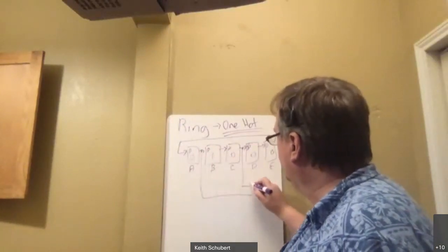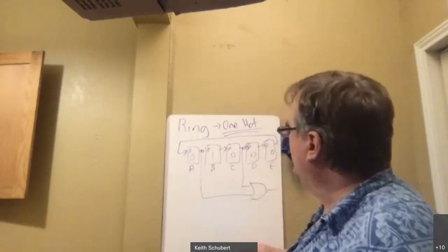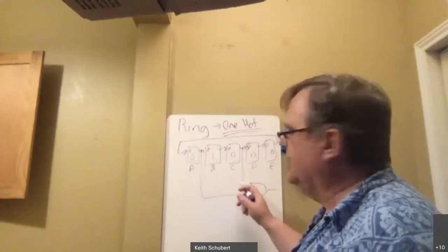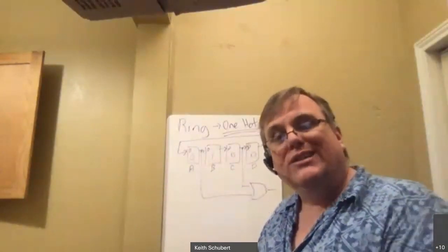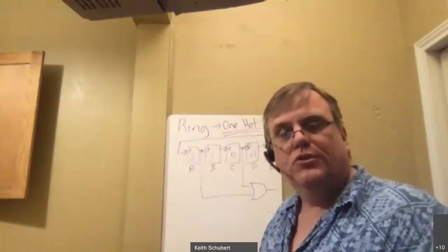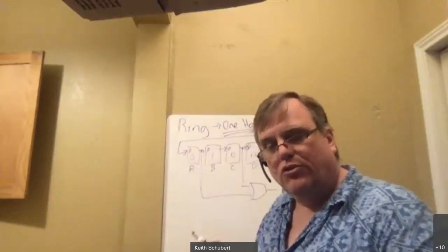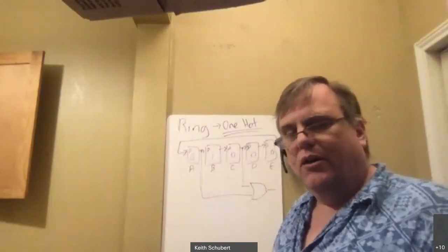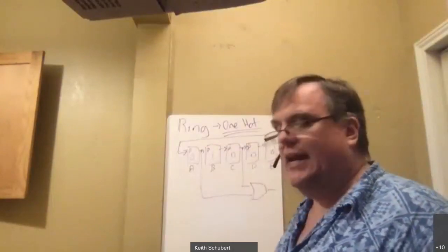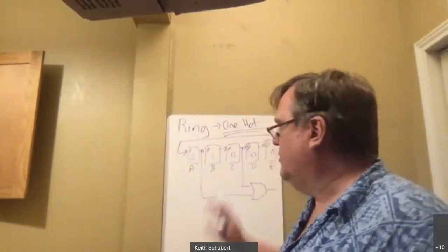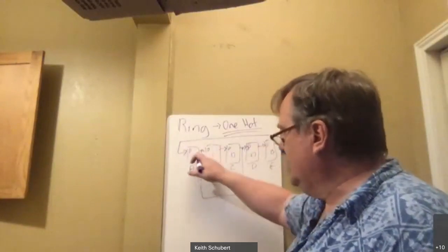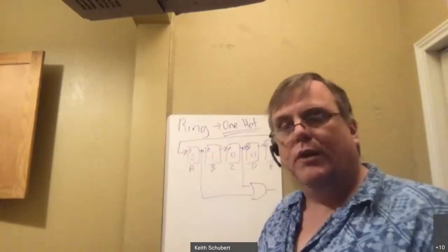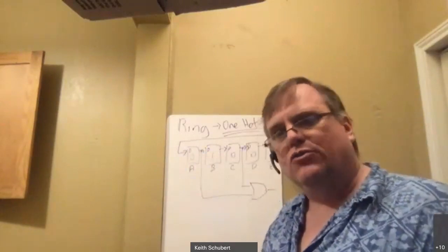So I can then take this and do that. So if I wanted a 1 output when I was in state A or state C, this is the way I can do the output. So you can see it's actually really nice to calculate outputs. Remember, when you're doing any of these type of register transfer level things, shifting from one register to the next, there's basically 3 types of building blocks. There's the memory, there's the thing that does the transition between states, and then there's the output logic. Those are the 3 basic chunks of anything that does register transfer level.